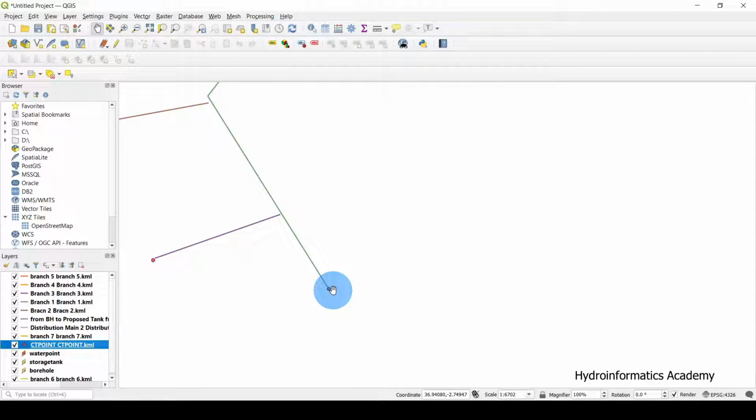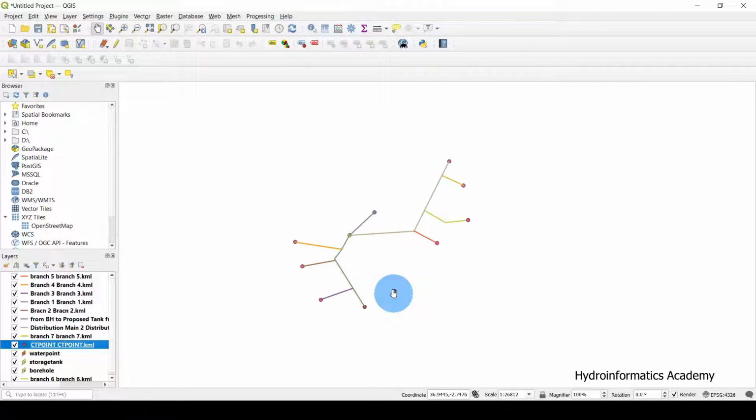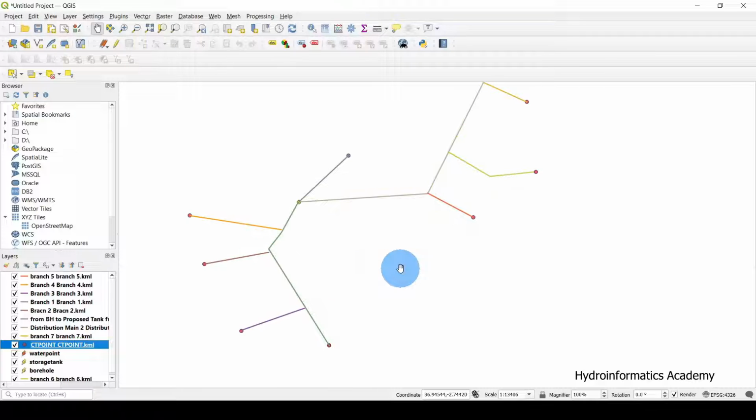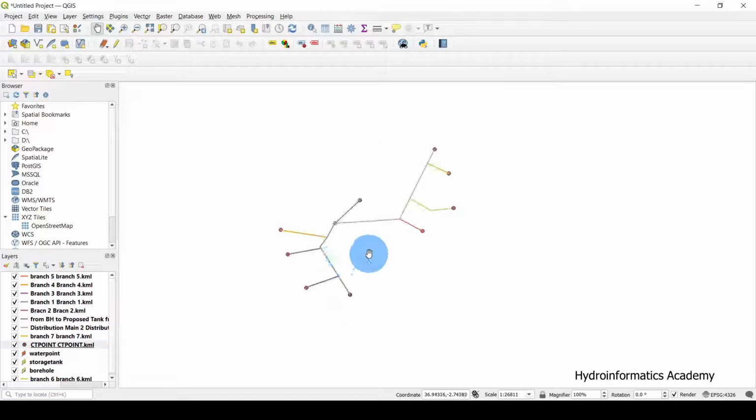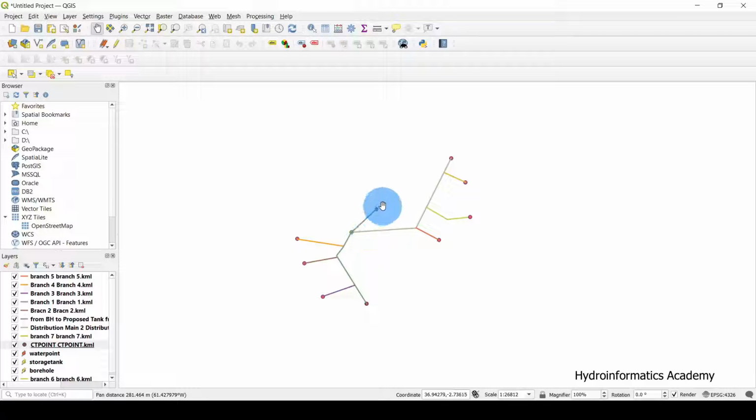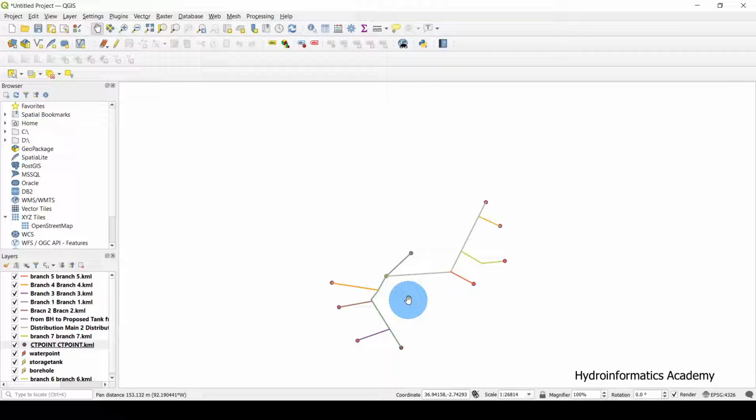Okay, so those are the options that you can use to introduce these points on our QGIS software. So from here, the next step that I need to do, remember, our intention here is to make sure that we create a map or a layout that will show how different structures in our water project will be allocated. So for now, what we have done so far, we introduced these points, and also we have imported our files in our QGIS software.